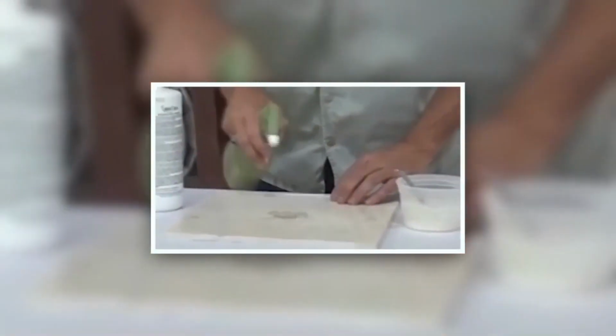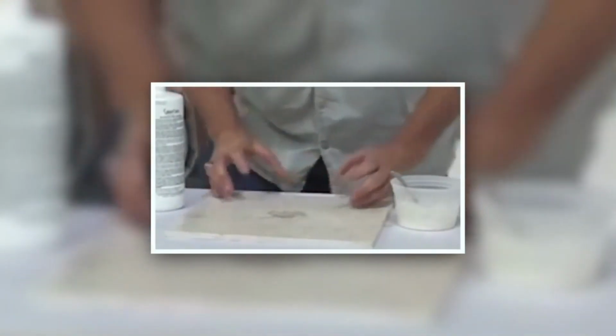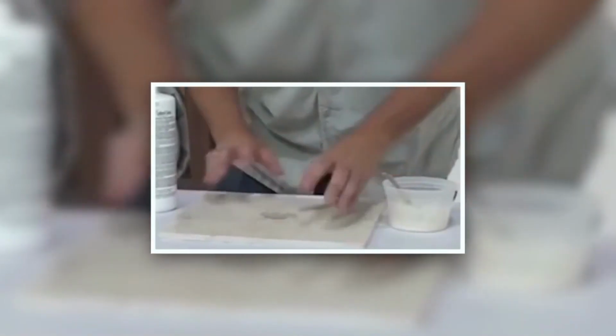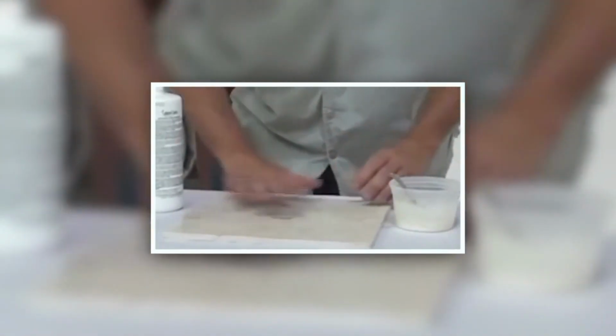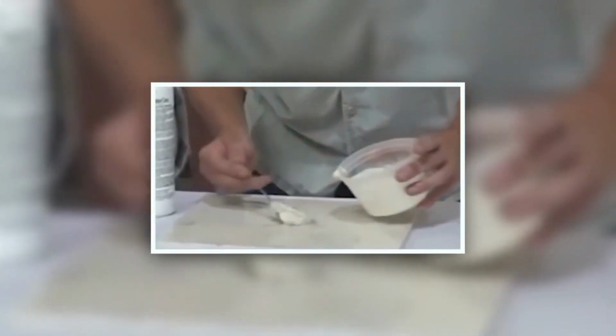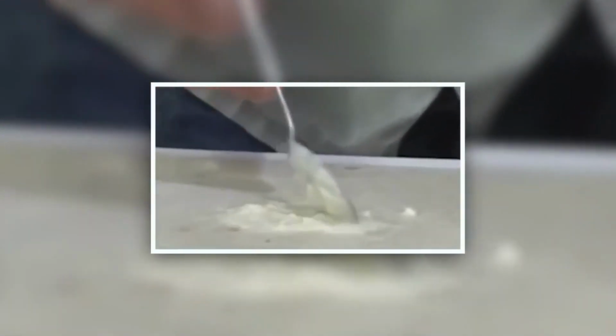Because stone is like a sponge, we are going to use some distilled water to wet the stained area first. This will isolate the stain and accelerate the stain removal. If we apply the poultice without wetting the area, the poultice will wick into the surrounding stone. Apply the paste about a tablespoon at a time, until it is 1/4 inch thick and extends about 1/2 inch beyond the edges of the stain.